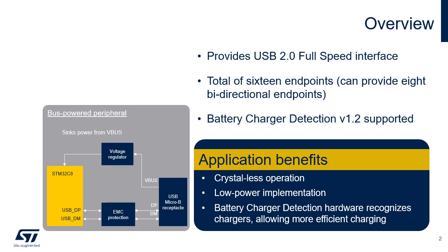It offers 8 bidirectional endpoints and is compatible with the Battery Charging Detection Specification version 1.2. Key advantages of this setup include crystal-less operation, energy efficiency, and faster charging, thanks to the integrated charger detection feature.